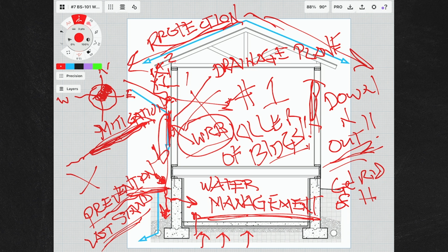It's actually, the basement is probably one of the hardest to detail, because there's a lot of money that can be spent on prevention down there, but if it's a relatively low risk, then you might not have to spend all of that money in that budget. So the game in the basement is really one of what is my risk, or what is the potential for it to get wet.